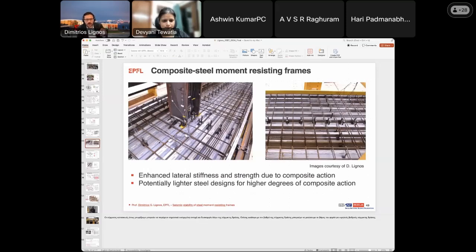The reason we try to avoid this is because if you weld a shear stud in this region, the weld itself could create a defect, and this defect could potentially be problematic because it may induce fracture. So I think this rule could still remain like this.